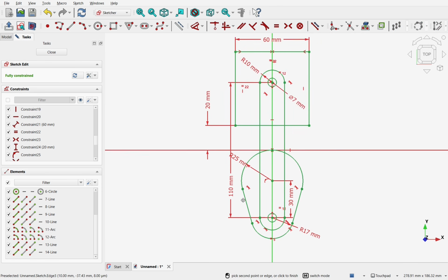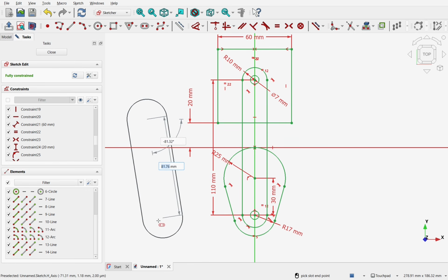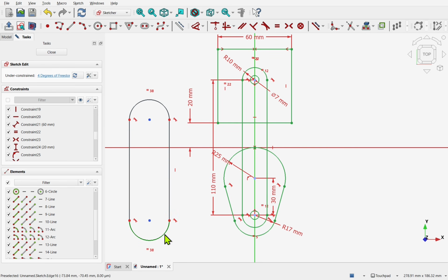We have 3 parts so far: piston head, the link arm, and the counterweight. Let's create the mount. Right click to make sure our tools are cancelled. For this, we use another slot geometry. Add that in. Right click to cancel the tool. We'll take the arc of the slot geometry, click on it, and hit delete on the keyboard. This is now open, known as an open wire.